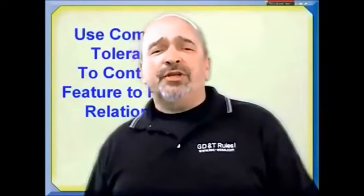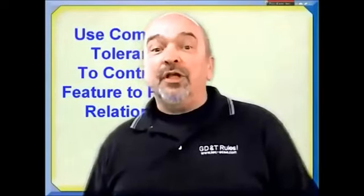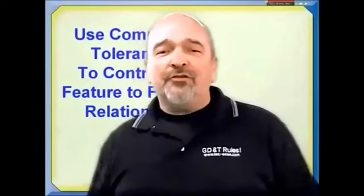I think I could do a tip on composite tolerancing every month. I received 2 composite questions just this past week. One of the questions was, what's the difference between having an orientation tolerance as a second segment of a position control and using composite position? Well, we have this rule that says you're tightening up the location of the features within the pattern if you use composite. Let's take a look at these 2 drawings.